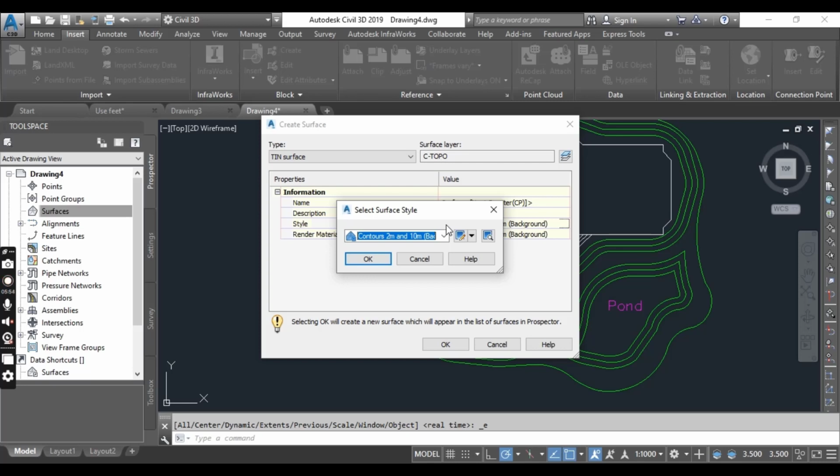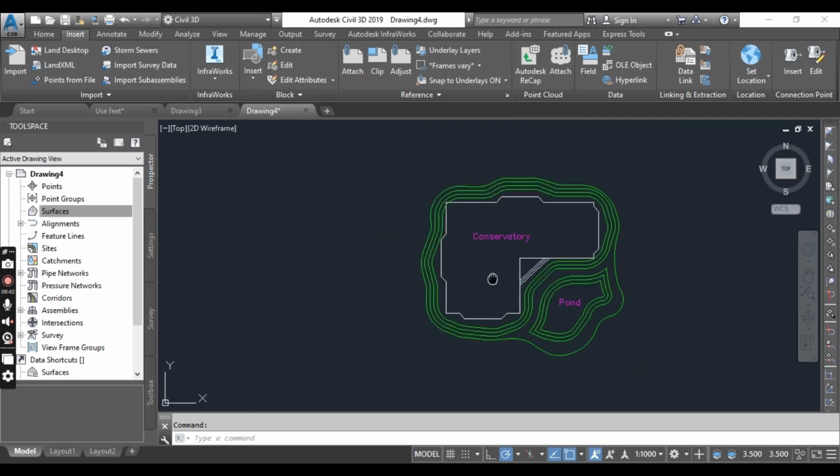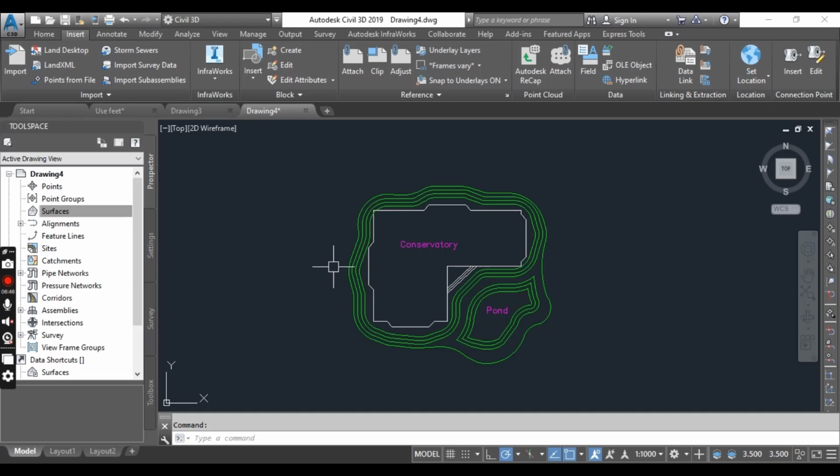At this point, you can now work on the drawing in Civil 3D without recreating any established standard. Everything from the outside source has come in, including blocks, layers, and dimension styles, but they will not override any of your blocks, layers or styles if they happen to have the same name. You must keep in mind that if the drawings are in different coordinate systems, the previously mentioned workflow will not deliver the desired result. For those cases, the workflow is different and involves the use of AutoCAD Map tools. So in this video, you can see how we solve this issue when we get any AutoCAD file and want to work in Civil 3D.